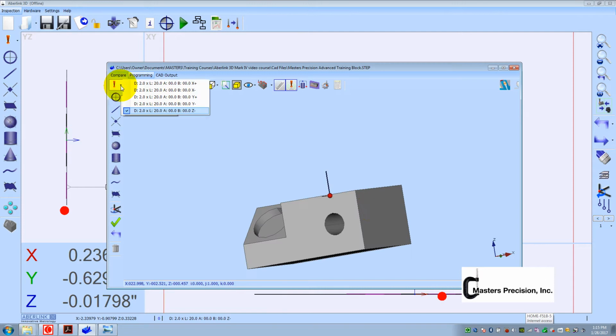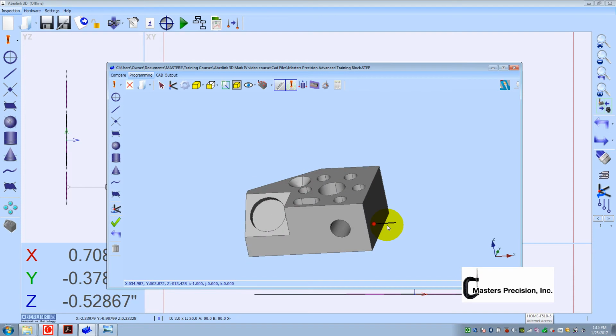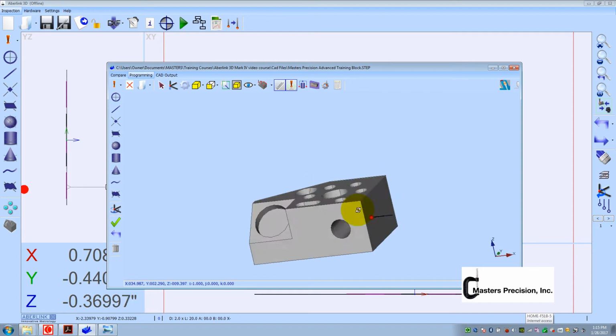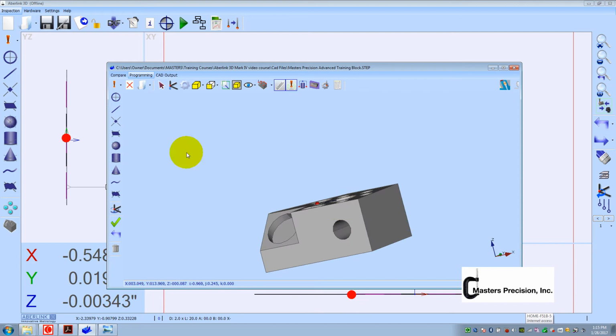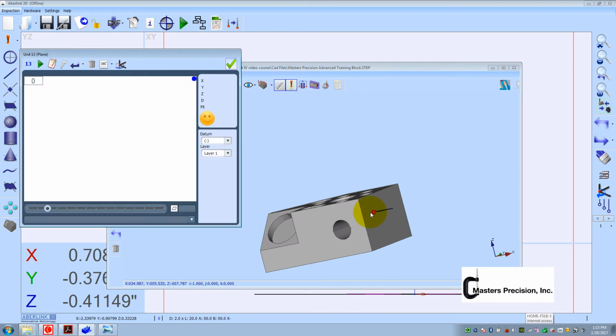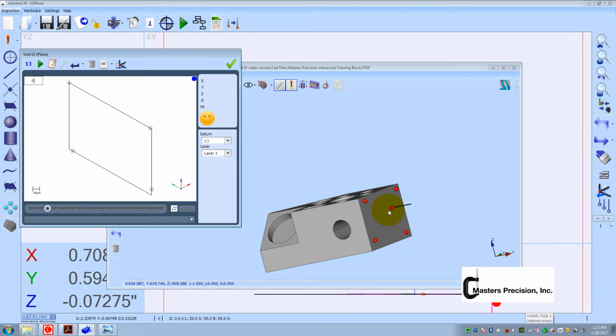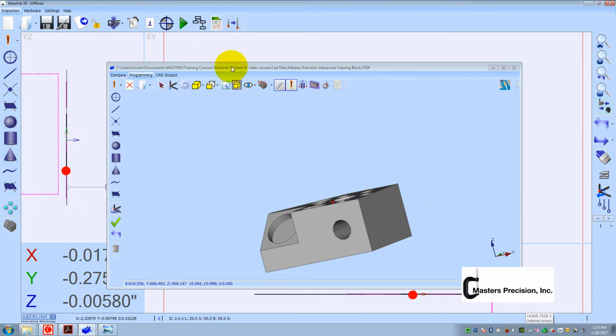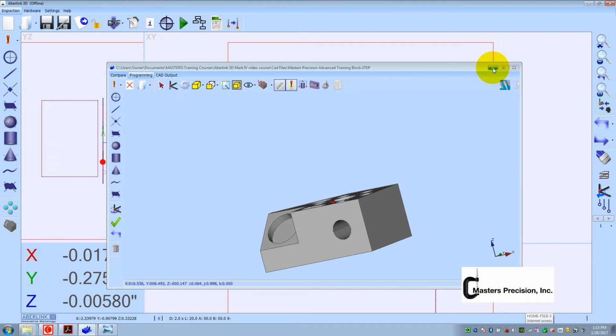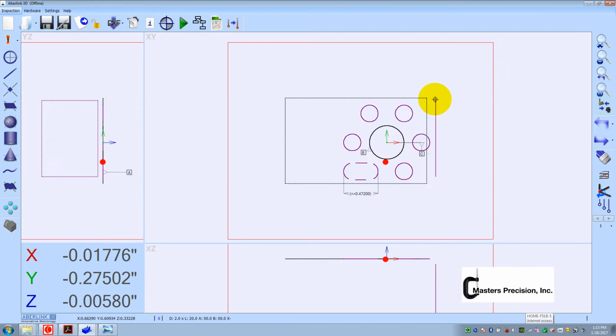So I'm going to choose my stylus, and it's going to be the one in the negative X. And all I'm doing is looking for my stem to be perpendicular to the surface. That's telling me that I have the right probe when using a star probe. Plane. Get up in the corners. Hit OK. If I minimize this, you can see the plane's right here.